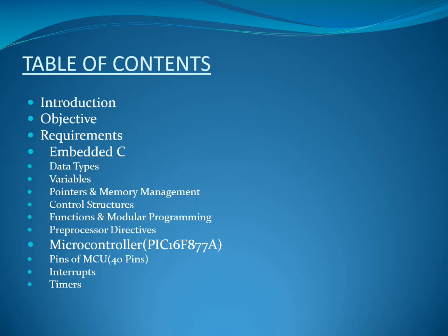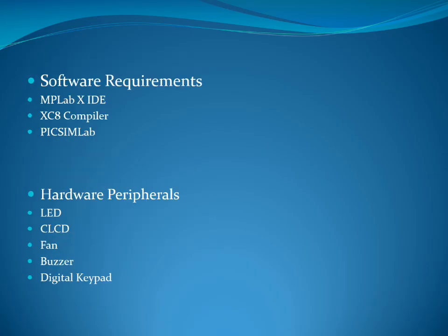We have specifically used the PIC16F877A microcontroller in this project, which consists of 40 pins. We have used MPLAB XIDE as the code editor, XC8 as the compiler, and to demonstrate the output we have used PICSIMLAB. We have also used some hardware peripherals like LED, CLCD, fan, buzzer and digital keypad.